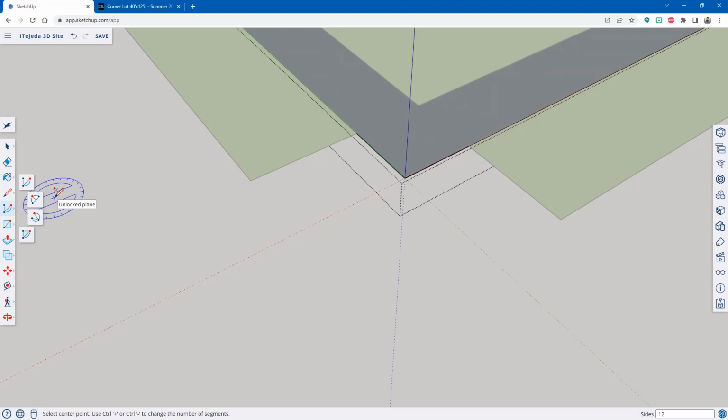They're not actually curved objects. So I want to change that number of sides to a higher number. All I want to do is simply change it to 24 at the very least. So I've typed in 24. And now I'm ready to begin.